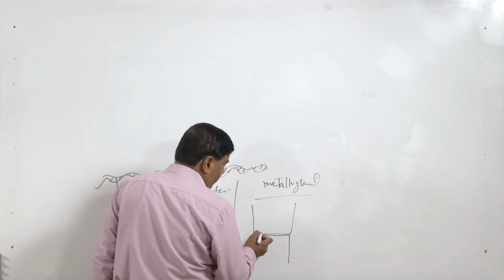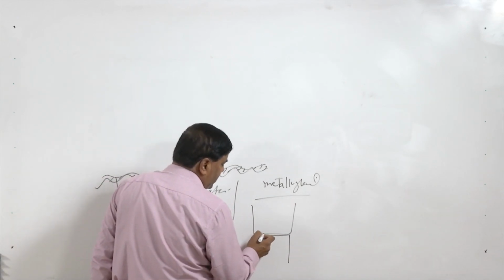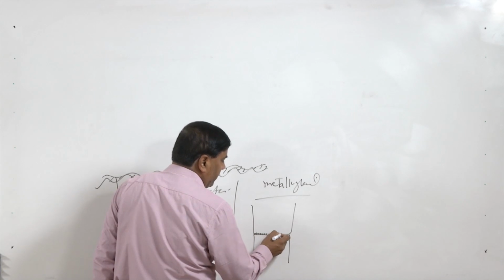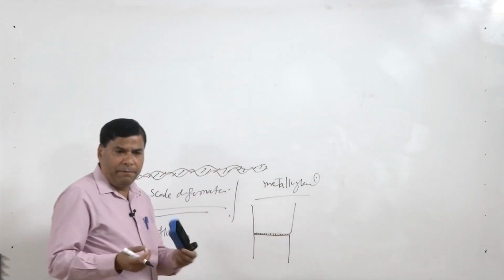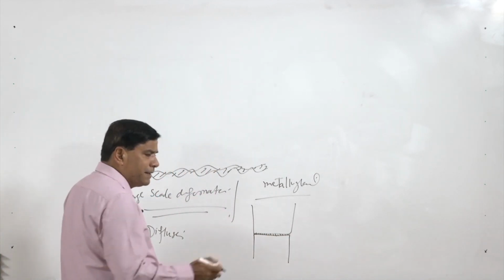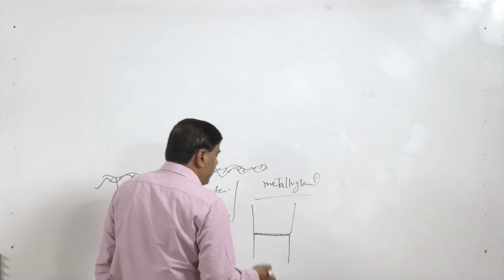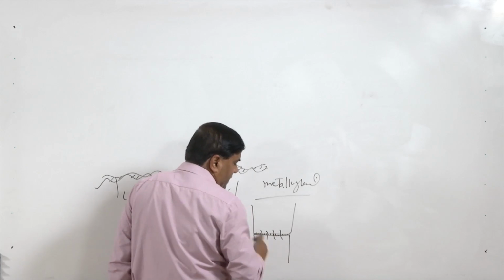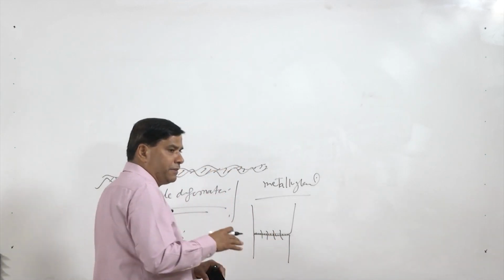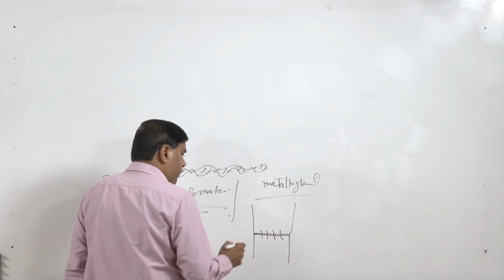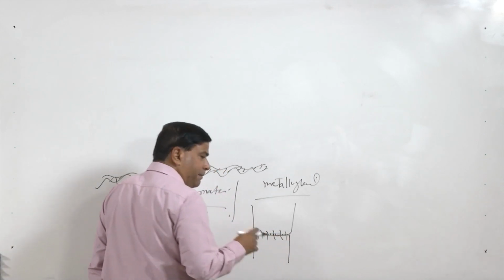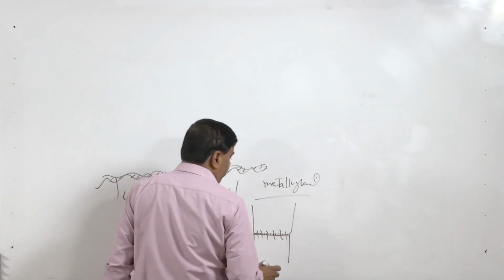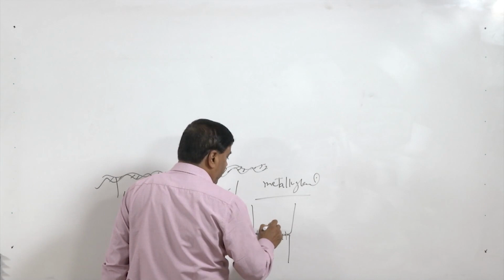So, here first the gap is closed through the deformation of the peaks and valleys by the creep, by the yielding, and then the diffusion across the interface facilitates the formation of the grain boundaries for developing the metallurgical continuity and metallurgical bond across the interface.